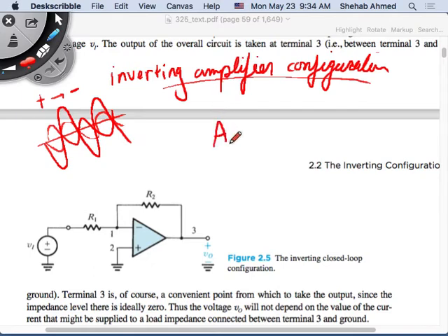We were talking about A being the open loop gain. So now we will talk about a new gain, A_CL, whatever we call it. It's going to be the closed loop gain, right? So the nice thing is the closed loop gains are going to be defined. We're going to have a closed loop gain of 2, 3, versus before we had an open loop gain of infinity. What does infinity mean? Nothing, right? It's not defined.